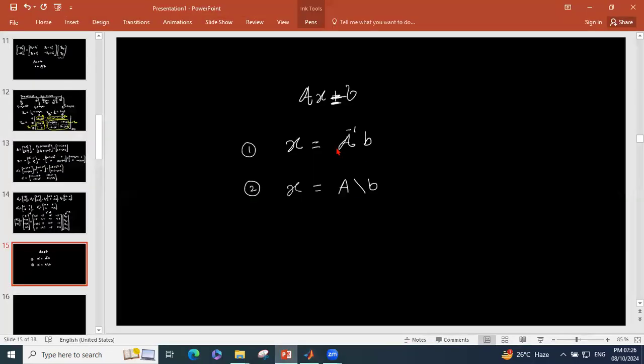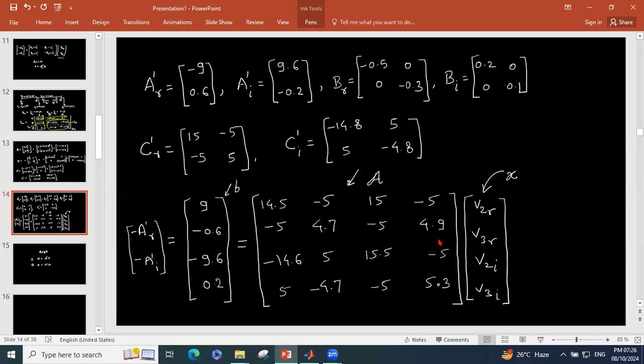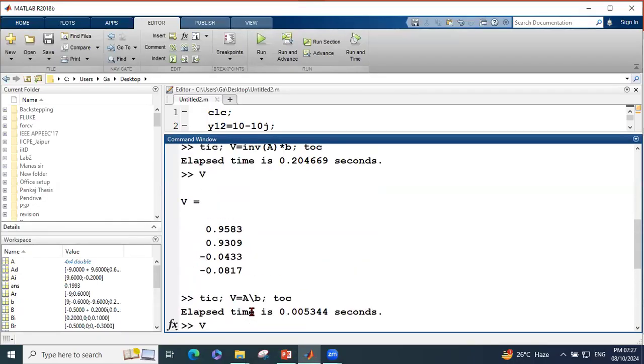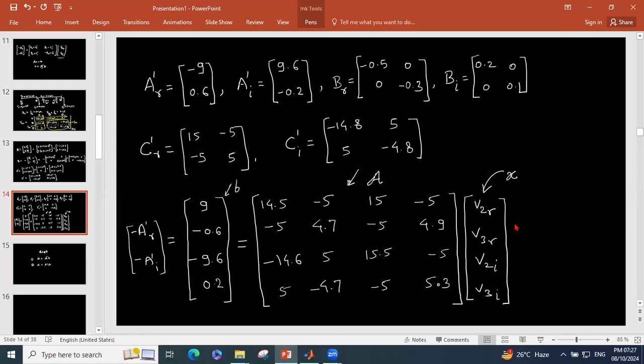So in power systems we don't prefer taking the inverse of a matrix to solve for unknowns, but we do it by the LU decomposition method as discussed in the earlier class. This was one of the simplest methods by which we can obtain a linearized form of the load flow equation and solve it in just one simple iteration. There is no need to perform any other iteration. In just one iteration, we got the answer. So you can go ahead and compare this with the actual backward forward sweep load flow or any other method that we have covered in the class, and compare with the help of linearization how much accuracy we are getting as compared to the backward forward sweep or any other load flow method, which is the accurate method. So you can go ahead and do that kind of comparison. Okay, so we will stop here.